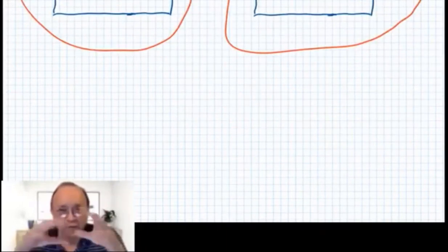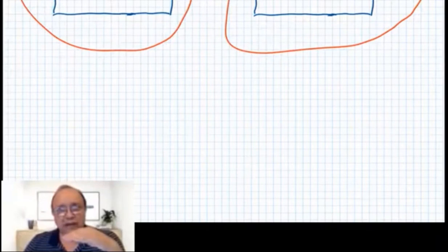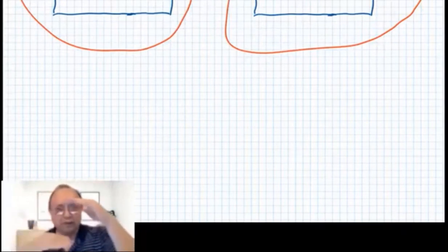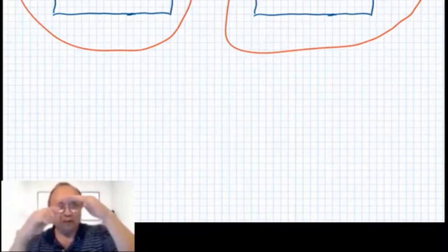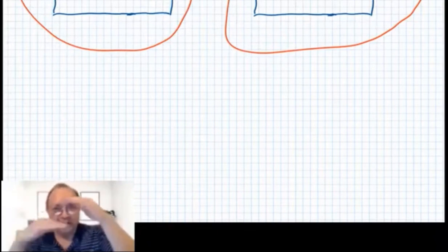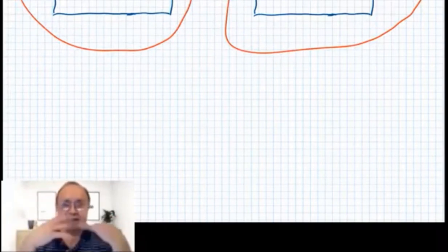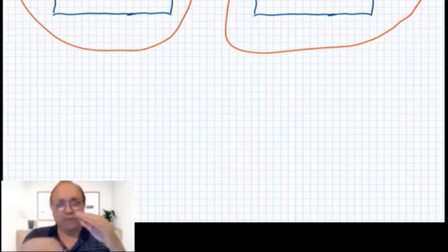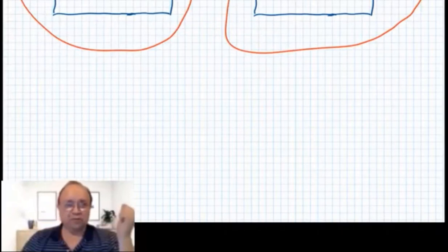I'm talking about this concept of moving a force out of the line of action. If I move the force out of the line of action, I cannot just move it. When I move it, I have to pay a price. I have to apply a moment because of the motion outside of the line of action. The force was applying a moment with respect to the new position. So when I move the force to the new position, I have to apply artificially a moment to compensate for the fact that the force in the new position is not applying that moment anymore. So in order to have the same conditions, I have to have the force in the new position plus the moment that was previously applied due to the previous position of the force. Okay, and the moment is equal to the force times the distance to the new position.